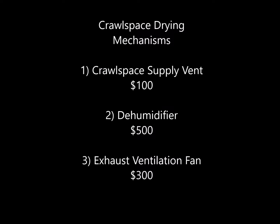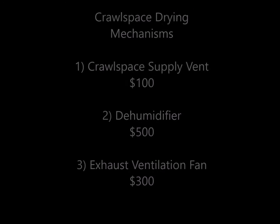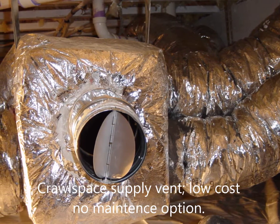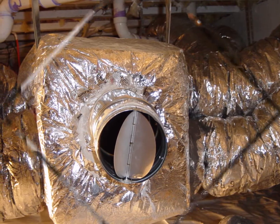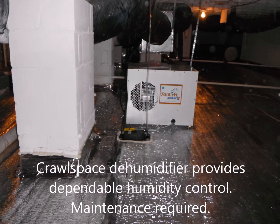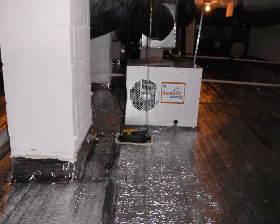Crawlspace drying mechanisms consist of three: the crawlspace supply vent, a dehumidifier, or an exhaust ventilation fan. Crawlspace supply vents are a low cost and no maintenance option. Crawlspace dehumidifiers provide dependable humidity control, yet require maintenance.